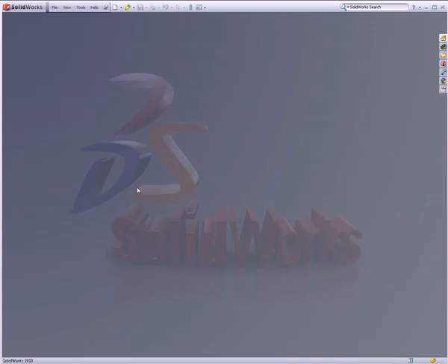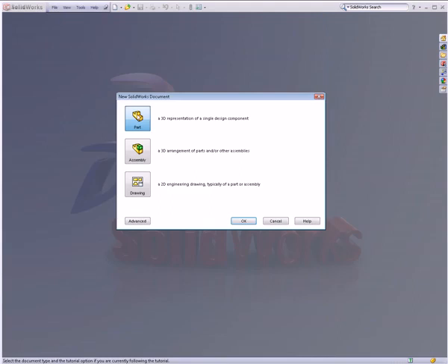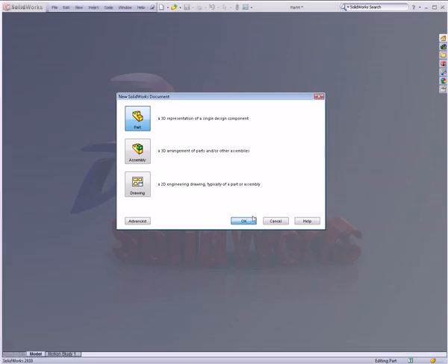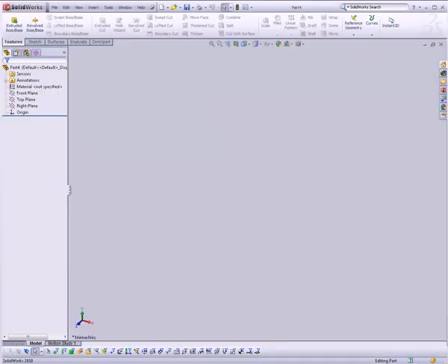So let's go ahead and take a quick tour of the SolidWorks interface. Let's go to File, New, and we're going to create a part and click OK. This is going to give us a giant blank viewport because we have a blank model. We haven't made anything yet. And over on the left we have a list that has some stuff in it that we don't really care about, except there are a few planes here that will be useful to us, front, top, and a right plane.